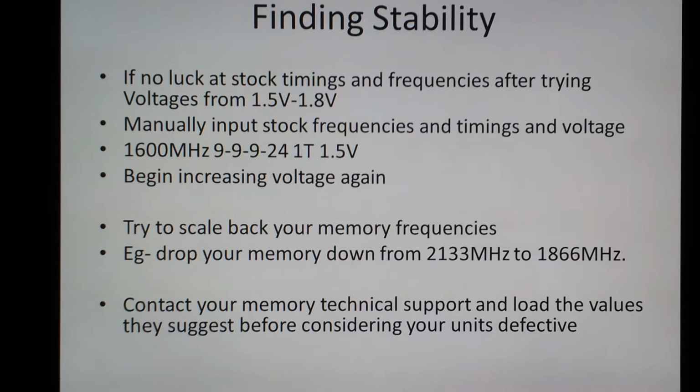If still no luck whatsoever, contact your memory technical support and load the values that they suggest. Once again, they may only suggest or recommend the JEDEC standard, which is kind of crappy. So if you bought a 2400 megahertz kit, they might suggest loading values of 1333. So once again, if you're considering buying a kit, maybe contact the manufacturer technical support team and see what they will or will not officially support before you buy a kit, and try to load those values up before you can consider your memory units defective.